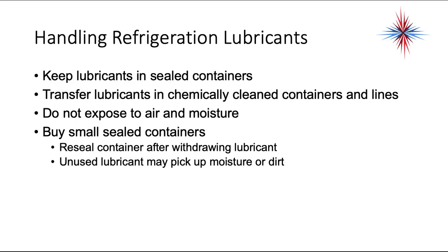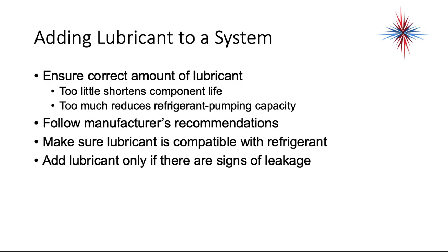When you handle refrigerant lubricants, you need to keep them in sealed containers. Most will absorb moisture. You need to transfer lubricants in chemically clean containers and lines. You don't want to expose them to air or moisture. You want to buy small sealed containers. Reseal the container after withdrawing the lubricant. Unused lubricant may pick up moisture or dirt, and you do not want moisture in a refrigeration system.